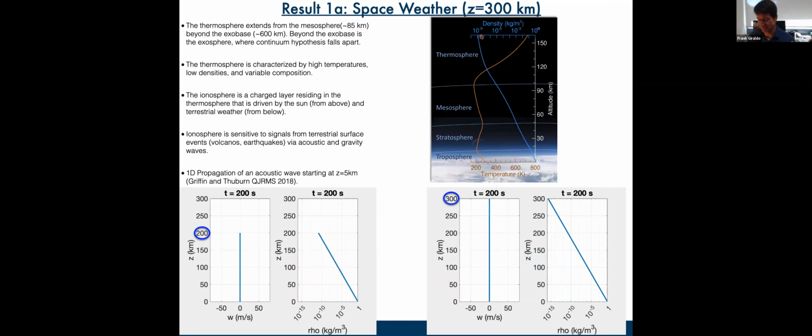300, it's tiny. And in fact, you can actually see it here in this example. Yeah, it's about 10 to the minus 15 at about 300 kilometers. So that's problematic, right? Because I said before that you have things like one over rho, whether you have a non-conserved form of the equations, or even from the conserved form of the equations, you're trying to extract a primitive variable for little u, for example, by dividing big U by rho. So there's all these problems that come up.